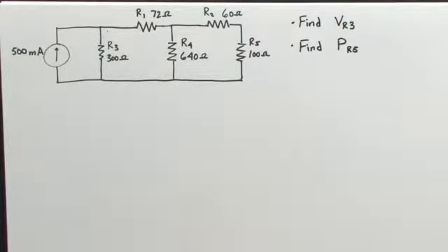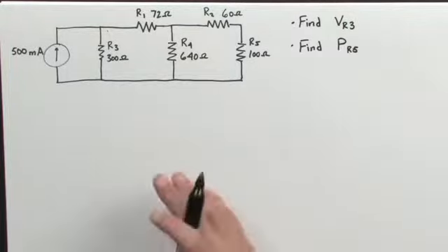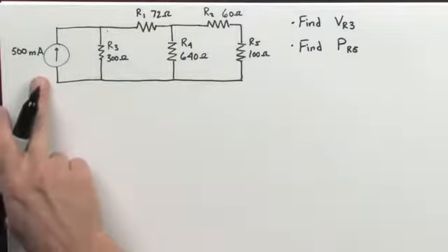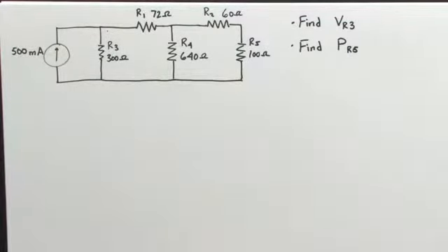So we can use the concept of equivalent resistance to analyze this entire circuit. Ultimately, what we would like to do is to reduce this circuit to an equivalent circuit comprised of 1 current supply and 1 equivalent resistance. So to do that, we're going to have to identify the resistors that are in series and parallel with each other. Remember that series elements are elements that have the same amount of current flowing through them, or see the same current flow, whereas parallel elements see the same potential difference or the same voltage across them, not necessarily the same amount of current.